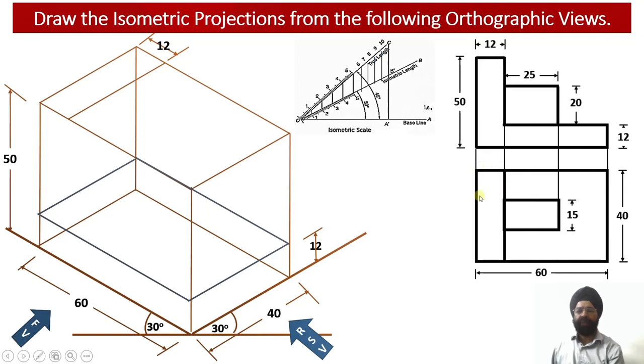So this is the top view projection which is going to give us the true shape of this rectangular portion of the vertical web, and this will be represented as an edge view in the front view. As we are going to look at the solid from the front side, this edge view will be visible to us from the front side.